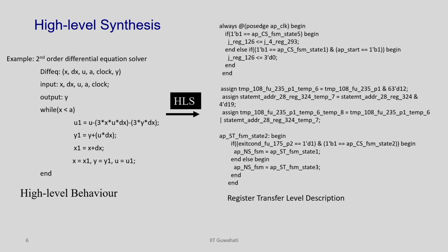Okay. So, what I am going to do in today's class specifically is this: we understand that high level synthesis is basically taking a C code and converting it into a register transfer level design, but how, right. We should try to go a little deeper into that topic. We have a C code where you have if else, for loops, branches, basic block operations and so on, and then you have a register transfer level design where you have a clock, registers, you are assigning the registers, you have a controller FSM, you decide what will be the next state, you have some data assignments between the wires. So many things are there, right.